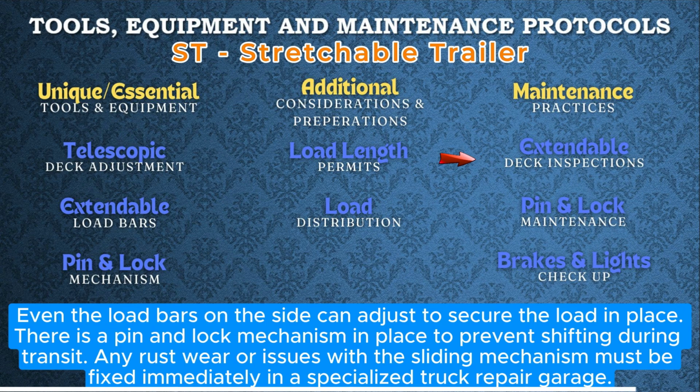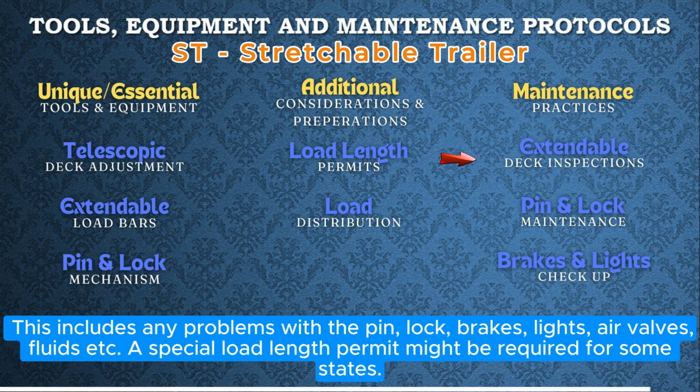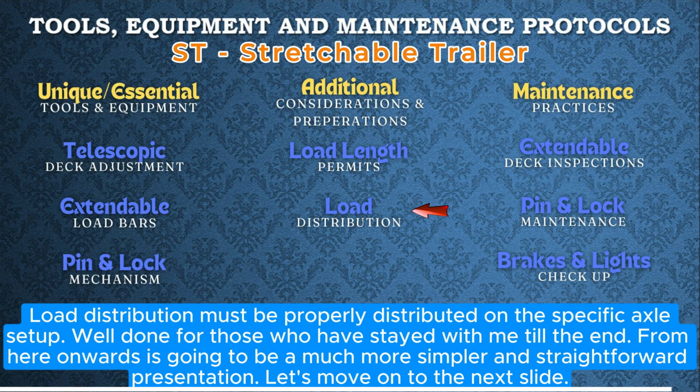Any rust, wear, or issues with the sliding mechanism must be fixed immediately in a specialized truck repair garage. This includes any problems with the pin, lock, brakes, lights, air valves, fluids, etc. A special road length permit might be required for some states. Load must be properly distributed on the specific axle setup.